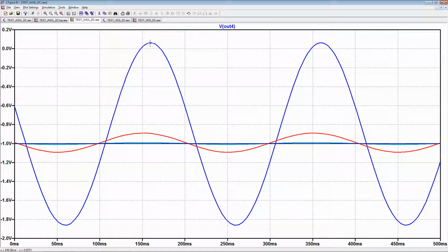So you just find the peak to peak of this, and notice it only goes up to a little over 0, goes lower here. You're just measuring peak to peak. That's due to the offset voltage, right? And then the sinusoid gets smaller and smaller, and because you're dividing by this output, as the peak to peak of this gets smaller and smaller, the gain goes up. And remember that we're multiplying it by 1,000.